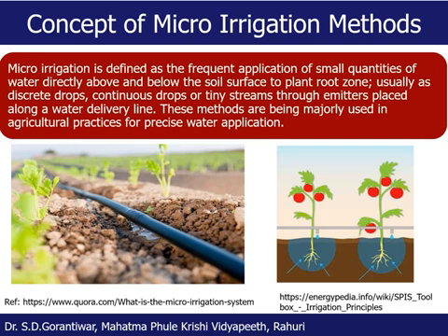But towards the end of the 2 weeks irrigation period, the water content in the root zone will again drop below the desirable level. We call this the allowable depletion level. It will drop below the allowable level or desired level, and it may reach up to the wilting point as well. And if it reaches the wilting point, the plant will be subjected to higher stress.